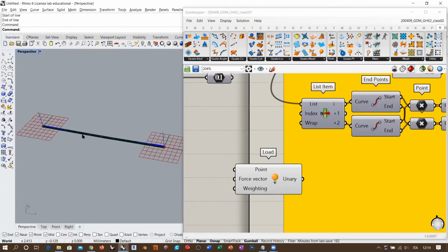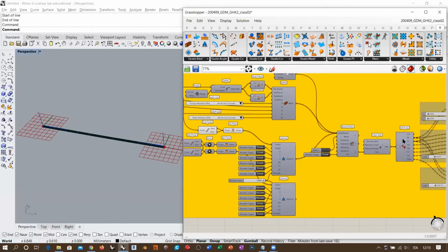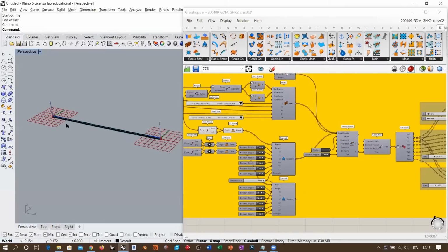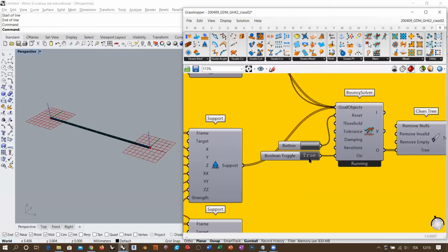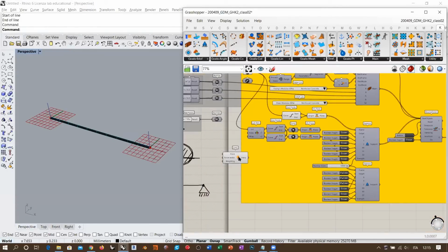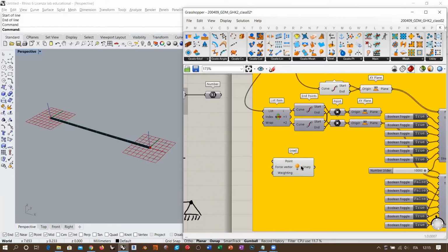If you orient an X load, for example, and you produce some kind of very high compression stress towards this extreme of the beam, then the simulation tends to become unstable. So when you see that the simulation starts to do some weird oscillation, and the graphics start to bounce around with extreme values or extreme amplitude coming out, then you better reset the simulation and start from scratch. But anyway, it's nice for you to try to implement a load scenario.